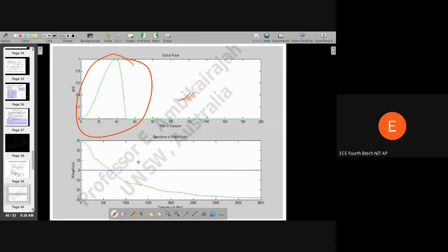And because it has low pass filter characteristics, it will have this kind of window function. If you see, it looks like a low pass filter. So this also looks like a window. It will also have a strong low pass filter characteristic. But in the time domain, it looks like this. So if you have e(n), which is a train of impulses, and you convolve it with this g(n), how is g(n) given in the z domain? It is a low pass filter.